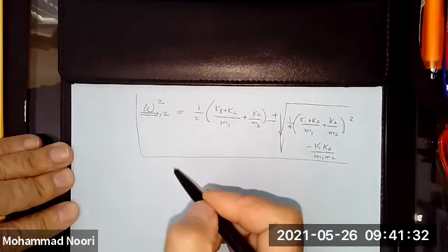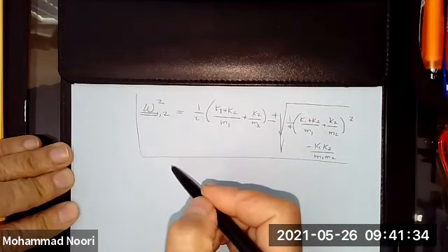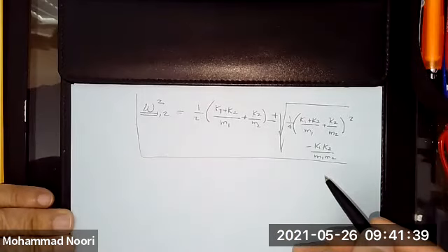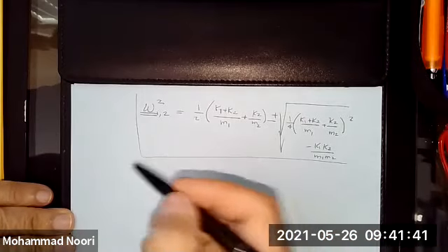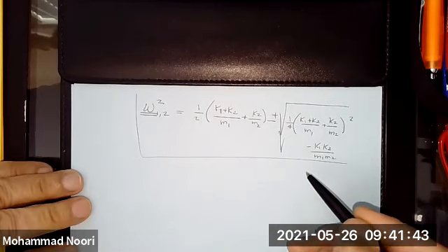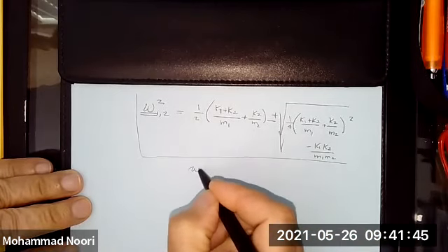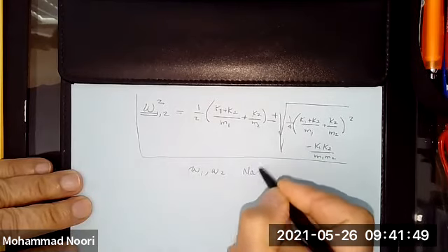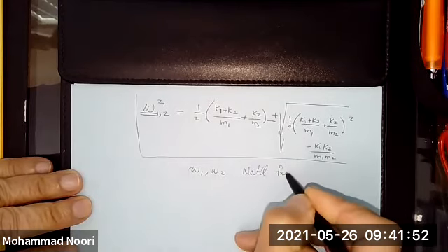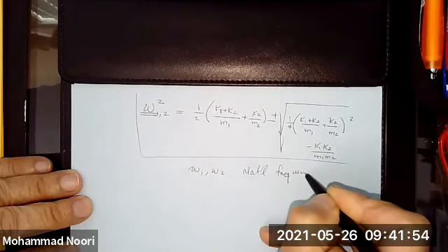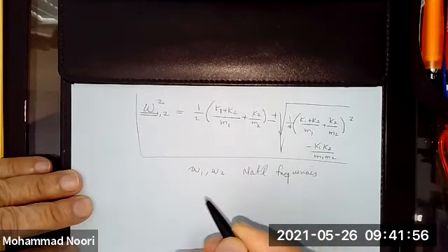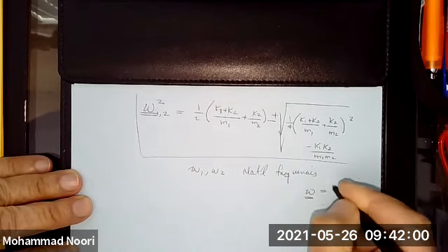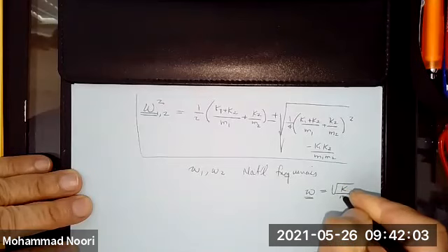So these two roots that correspond to those oscillatory motions for each degree of freedom, omega 1 and omega 2, are called the natural frequencies. In the case of a single degree of freedom system, you had one omega, which was the square root of K over M, right?